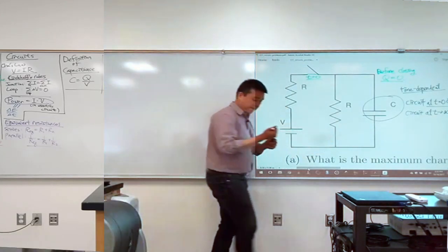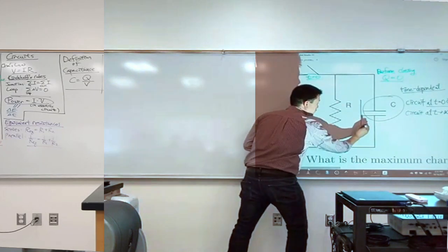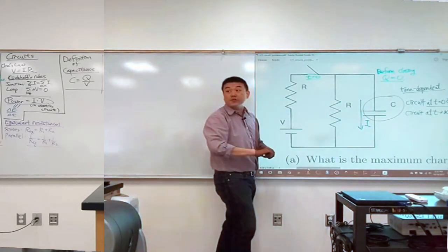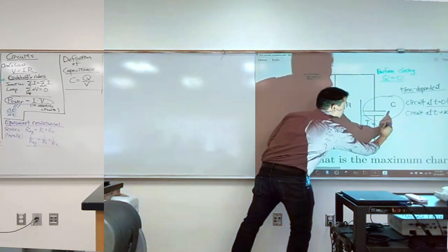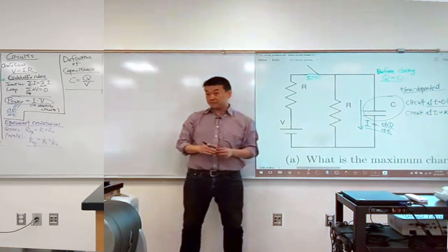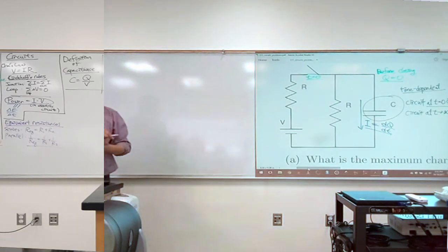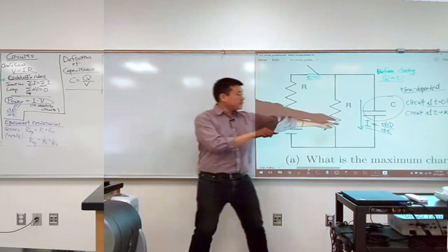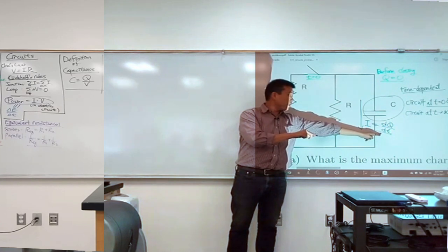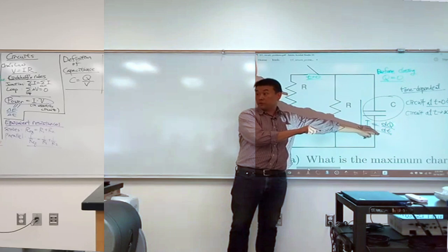If you are given some amount of current flowing through the capacitor, you can definitively say that it is equal to the rate of change of the charge accumulating on the capacitor. In most circumstances, this current is not going to be infinity. It's going to be some finite number, which means that if dt is equal to 0, then your dq will be 0.